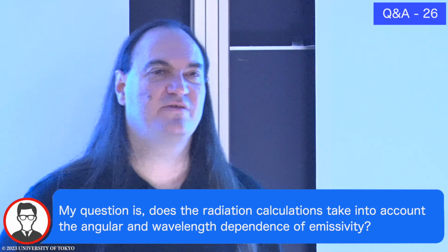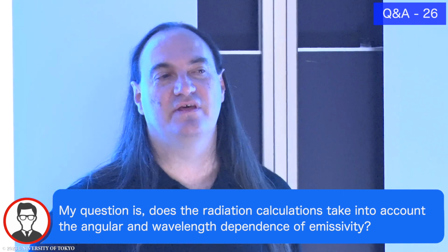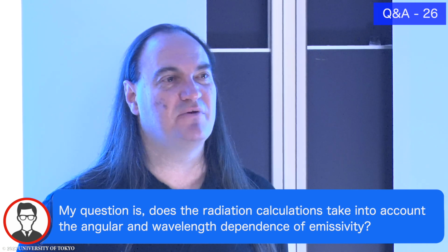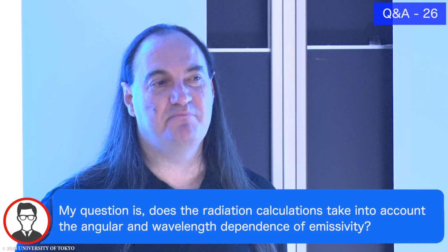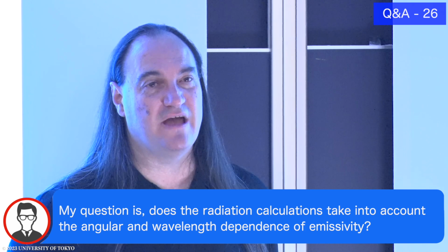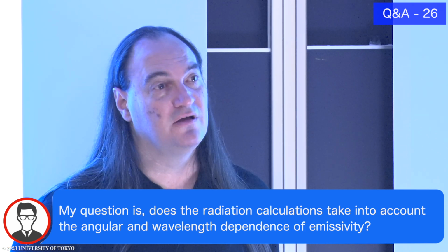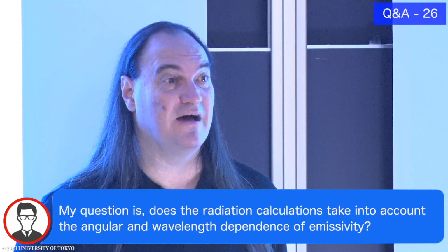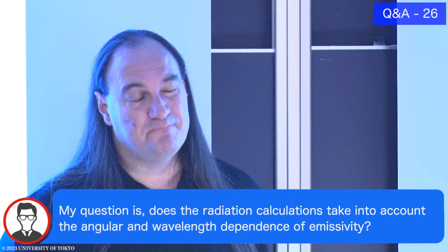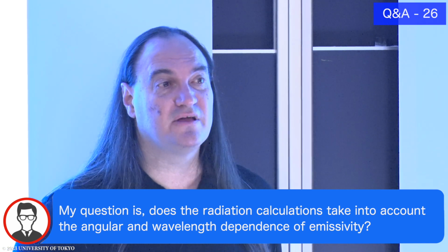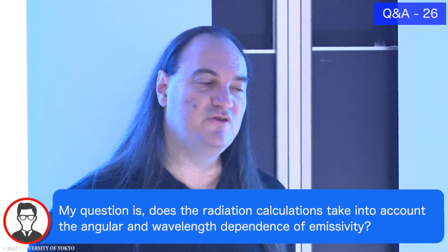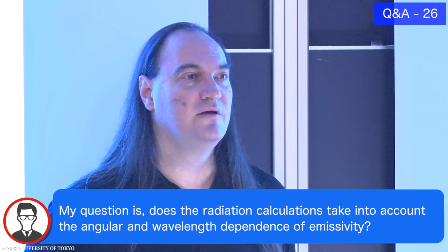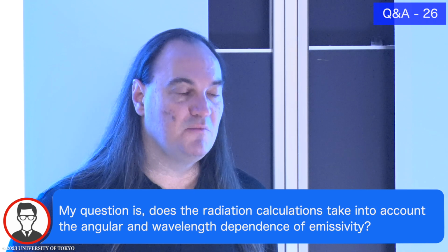So the wavelength dependence is not really handled in there. They have a checkbox for it, but I don't know that anybody has really used it. It basically is banding the wavelengths into two spectra, to the left of about 3 microns and to the right of about 3 microns. Generally speaking, it's probably good enough for most things, but if you do have a more complicated cryo type application, you might have to be more careful.